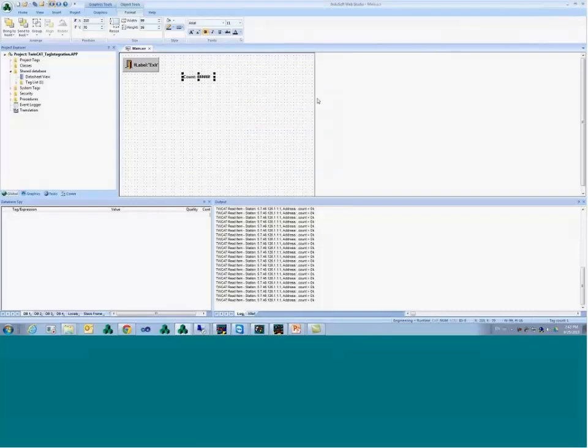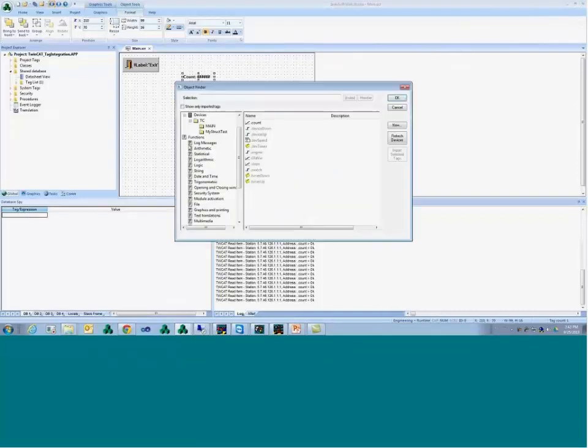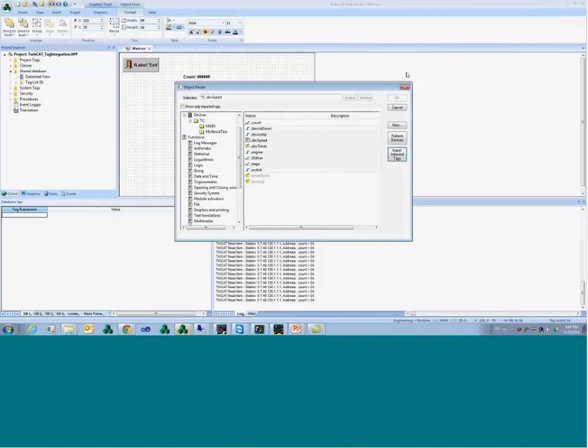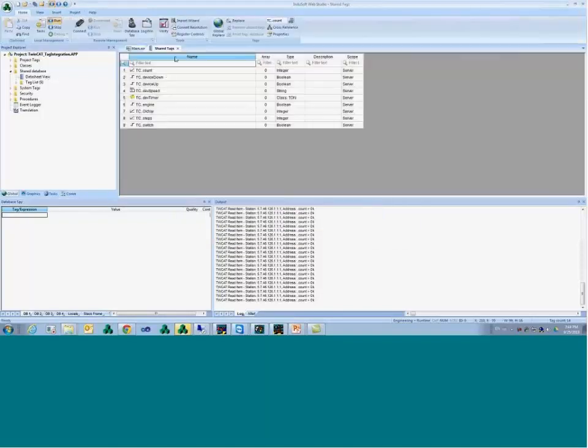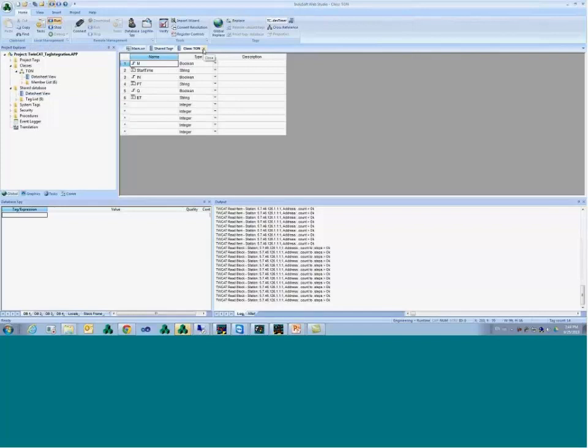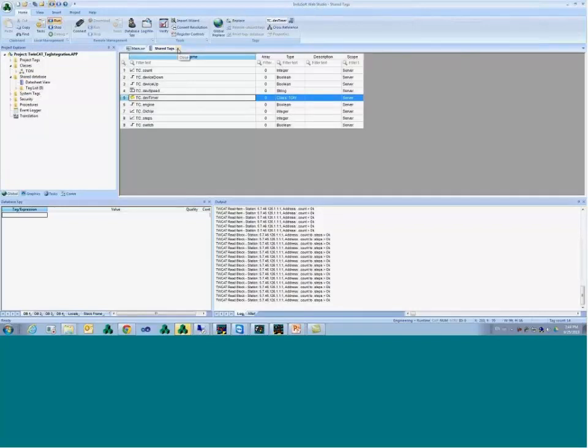You can do that, for instance, directly on the database SPI. So you open the object finder, you can select, so if I hold the control key, I can select more than one variable. So I'm going to import, for instance, the timers. I have here the dev speed. I click on this button, import selected tags. Confirm. They were added. So if I look here on my tags list, now I have all the tags imported, including the tag that is time on delay. We create automatically the class for that as well. All right, and we are communicating with them as well.